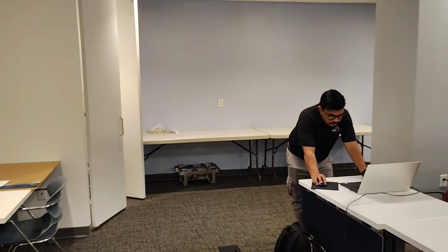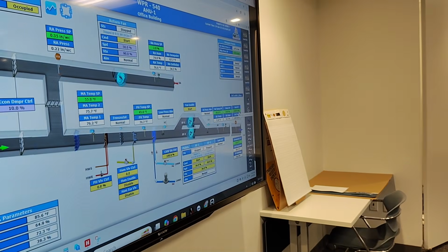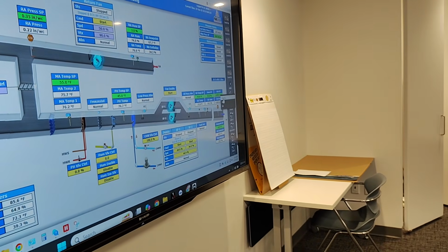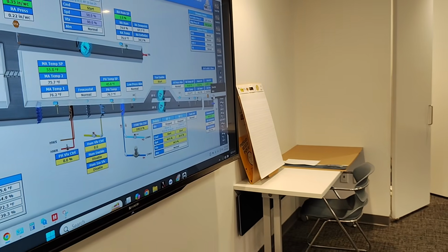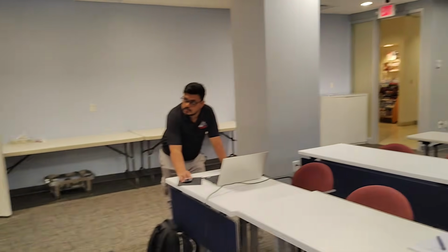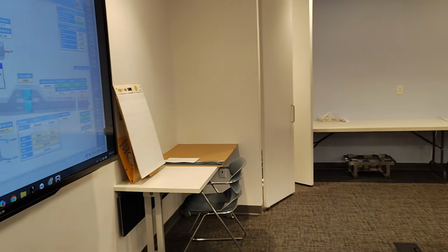Show them how to do the set point change on the static pressure again. All right, so go back to the air handler. Now tell them what you're doing. Right clicking, left clicking. I would be doing a right click here. You have override, auto, and set. Now, whenever it's a set point, those are the green ones. You want to use set because that's controlling the virtual point. We don't want to override. So you hit set. Now it's going to open the same window. Auto is relinquishing.